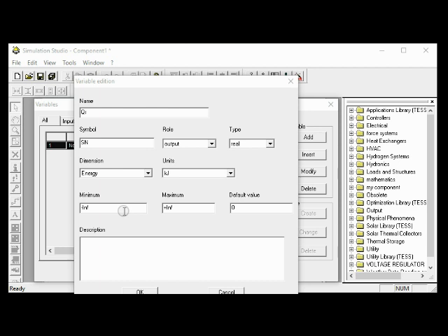These values will be used when the component model is placed into an assembly. The default value must be between the minimum value and the maximum value. The default value is replaced by the initial value for the input, and derivatives are suppressed for the output. These values must be given in the unit specified between the minimum value and maximum values.